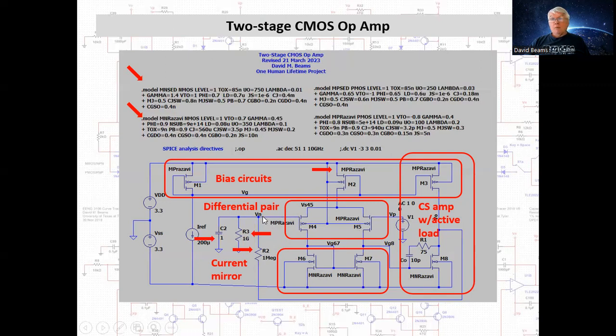the op-amp, when you go to do an analysis, the first thing LTSpice will do is determine the DC operating point. The inverting input will be at the same potential as the output of the op-amp. And so we'll find the proper DC operating point for all the op-amps in the model.